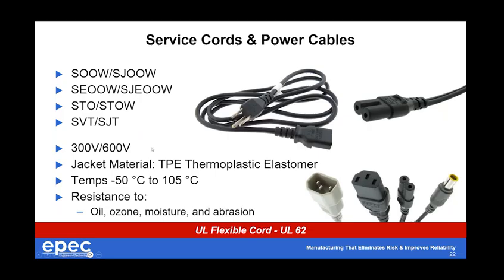SJEOOW. Each one of these has a very specific designation, with S meaning service cord, with the O being oil or moisture resistance, and the J signifying a junior level, which is basically a lower voltage threshold. But the majority of these all use TPE, also known as thermoplastic elastomer, which is an extremely common material in the extrusion of bulk wire.